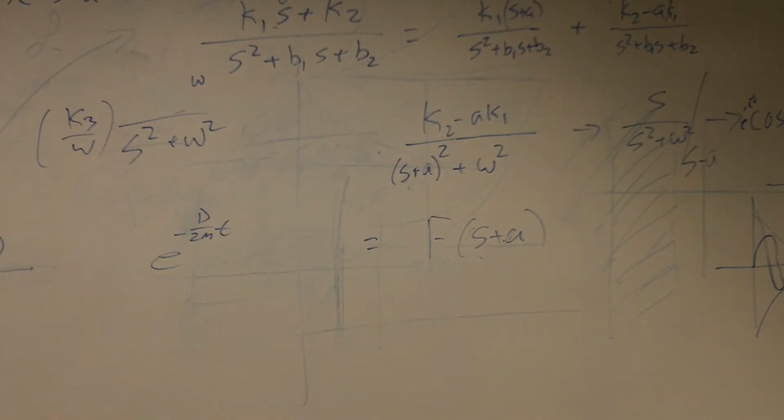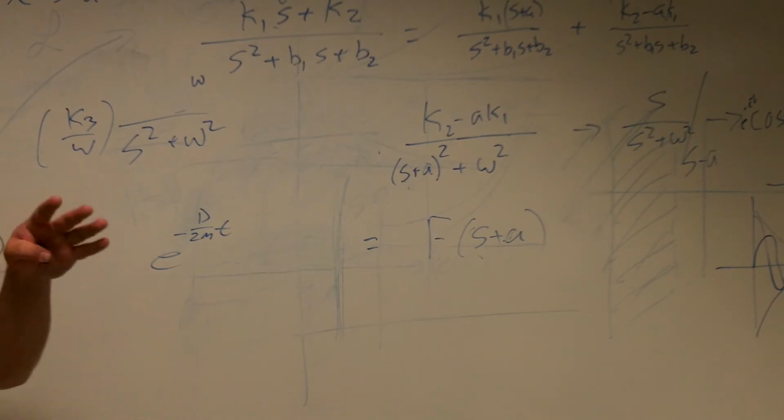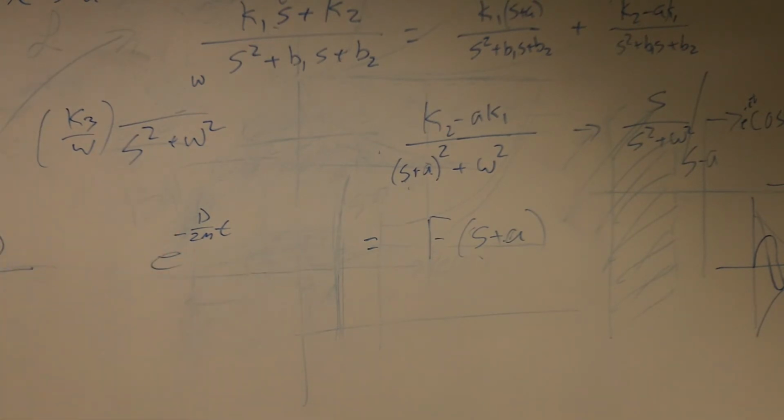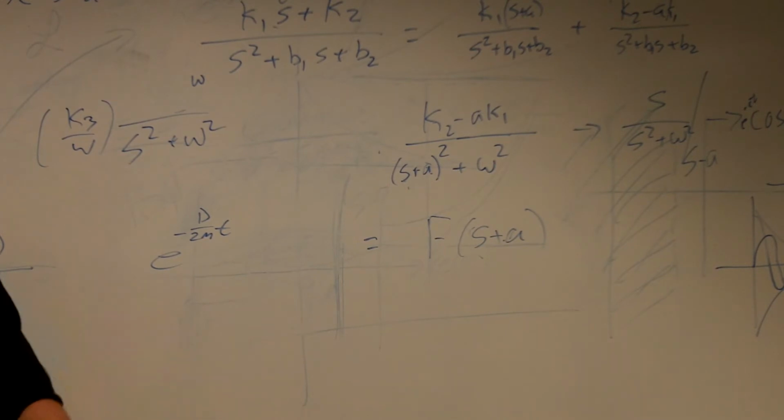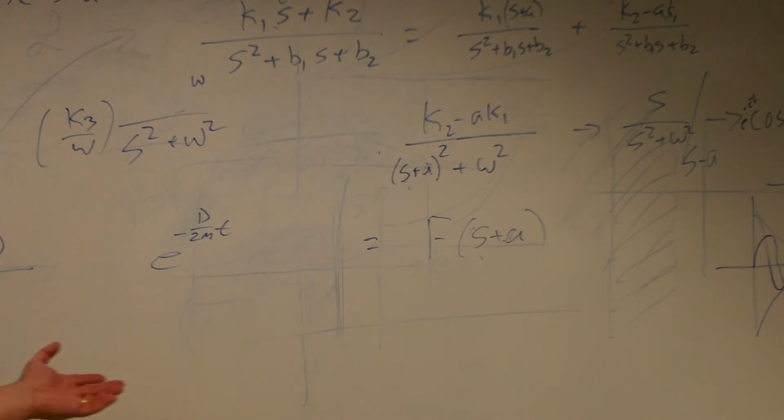And that's dependent on the damping. How much energy are you losing by rearranging the molecules in the dash pot, or if it's moving through air, the air being redistributed, and so on. The non-conservative force, because that's what dash pots are. The dampers are all non-conservative forces, because all your energy is non-recoverable. You just rearranged all the atoms inside the box, and it took energy to rearrange them, but rearranging them back doesn't give you the energy back out. So that's why it's called a non-conservative force.